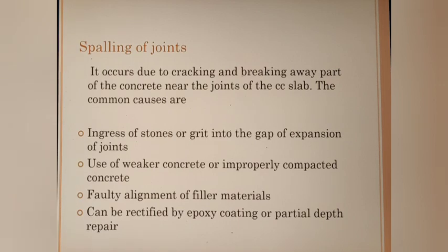And now this failure can be rectified by epoxy coating, or partial depth repair can be done. So epoxy coating can be used as the filler material. Second rectification method is you can repair the concrete up to a partial depth.